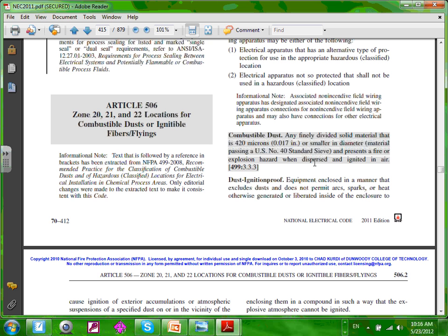If you are an estimator or project manager working in a hazardous location, you're talking about 50% extra in labor and material, at least for these locations. For the same branch circuit, guys, whether you put it in a hazardous location or non-hazardous location, Class 1, it could be twice as hard and twice as expensive to do the same branch circuit or the same magnetic starter or VFD and so forth. Any question for your friend Chad?